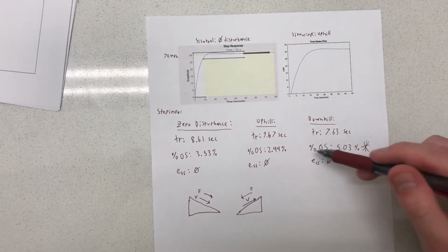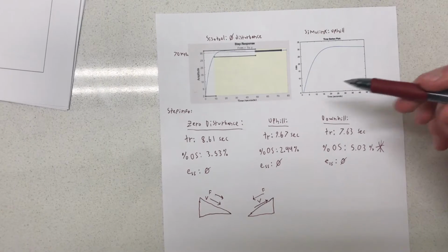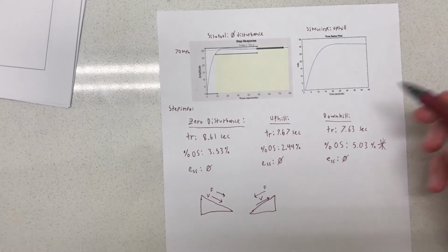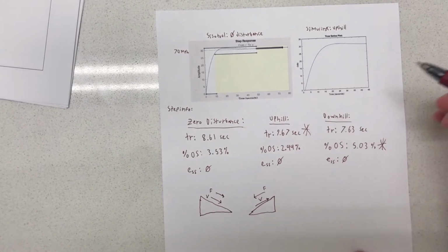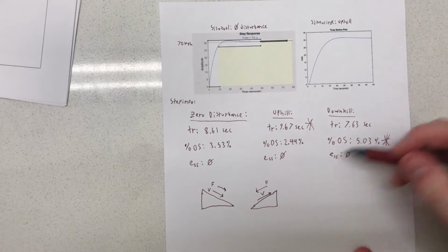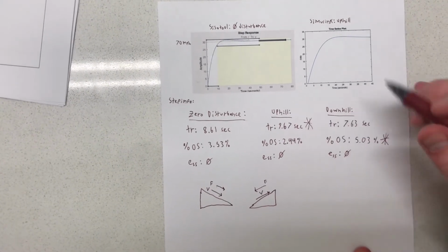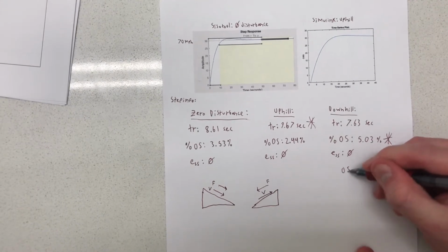In downhill, the overshoot is going to get really large, and in uphill, the rise time is going to get very large. If we were to alter the controller, we would start increasing this 9.67 second rise time. So instead of moving the error in handling both configurations over to this uphill rise time, we're going to accept a 0.03% exceeding of our overshoot.